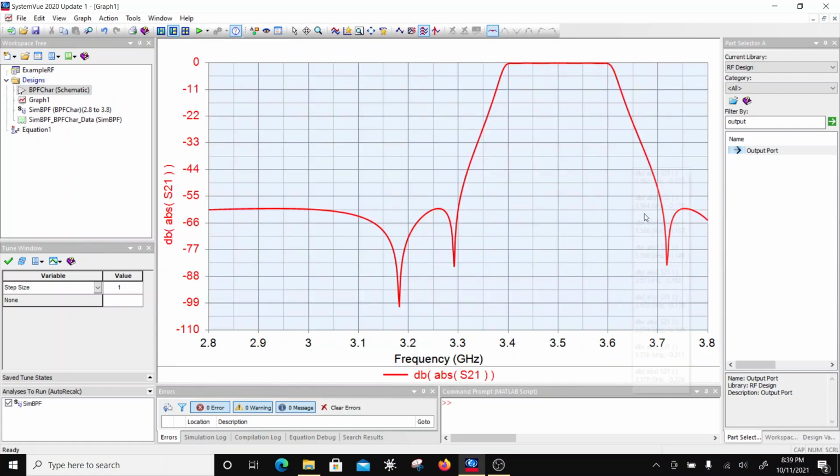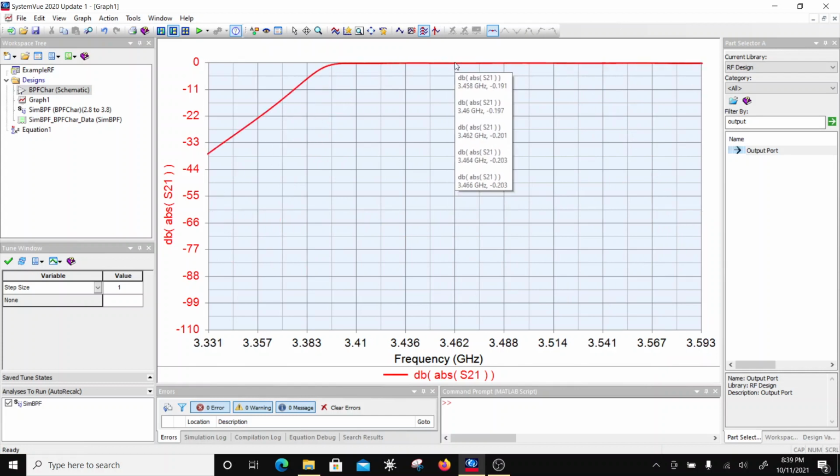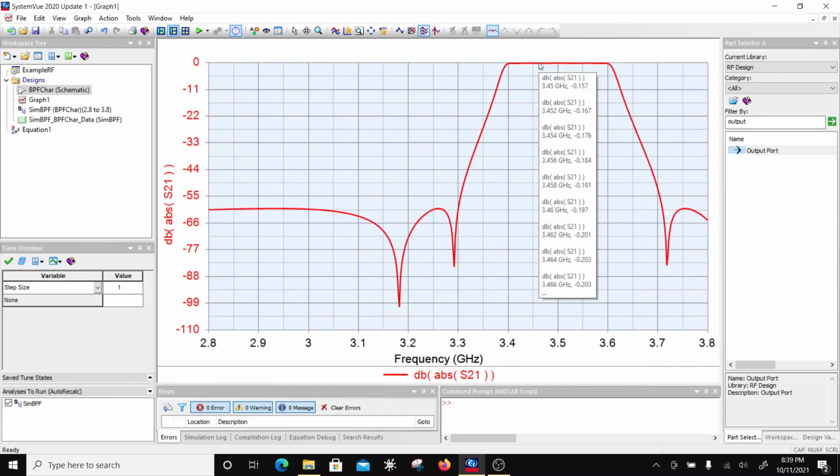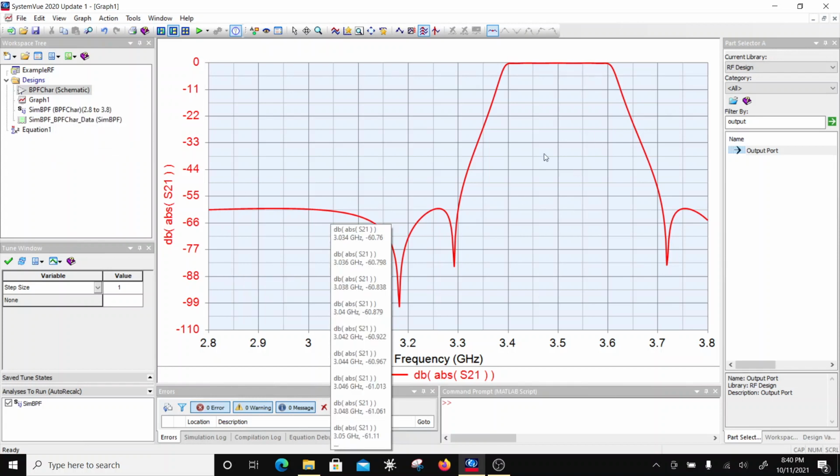That's your elliptic filter characteristics from 3.4 to 3.6 gigahertz, and here you would have a 0.1 dB ripple, which you can't see here, but that's what it is. Rather, I'll put from 3.2 to 4.2 gigahertz. Let me change this a little so that this thing is centered.